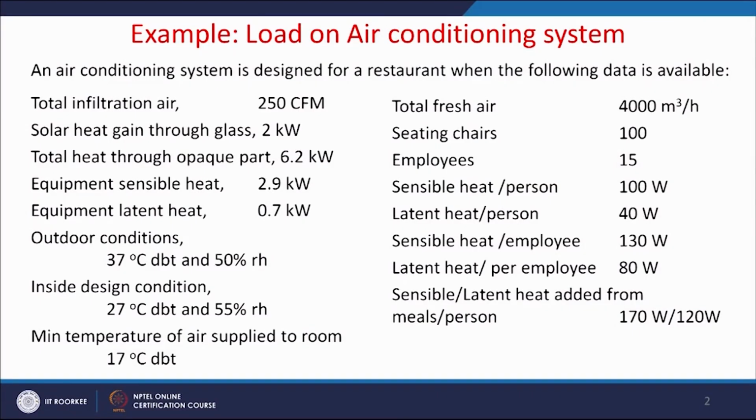Equipment sensible load: there may be a number of equipment like toaster, heaters, tube lights, computers, printers. So their load is 9.2 kilowatt. Equipment latent heat: some of the equipment do contribute towards latent heat also, like coffee maker, frying pans. So from this equipment a little latent heat is also added into the room.